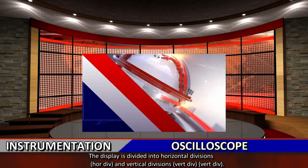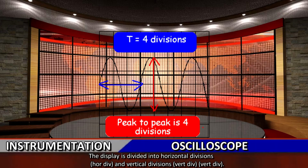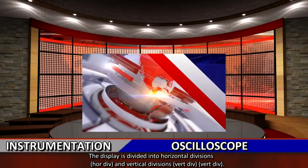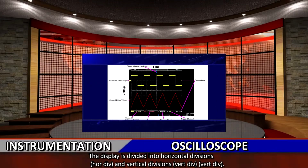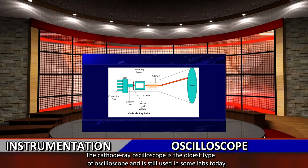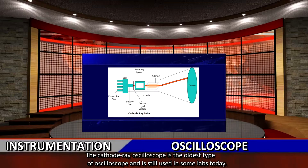The display is divided into horizontal divisions and vertical divisions. On the horizontal scale, the time is displayed from left to right. Instantaneous voltage is displayed on a vertical scale with positive values ascending and negative values descending. The cathode ray oscilloscope is the oldest type of oscilloscope and is still used in some laboratories nowadays.